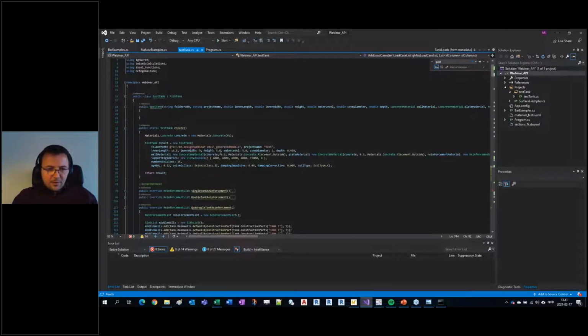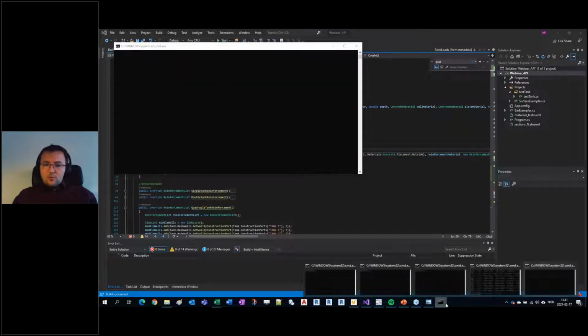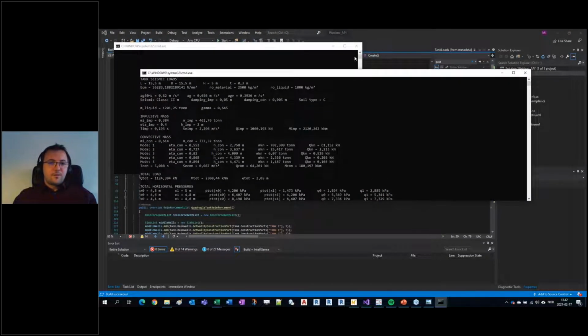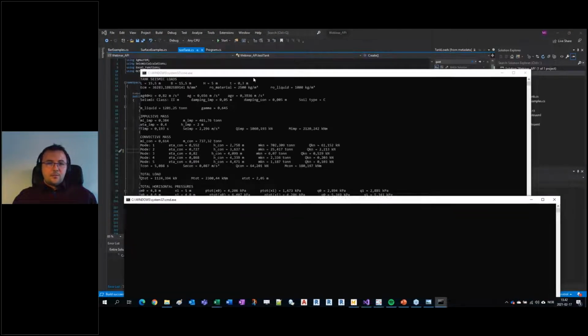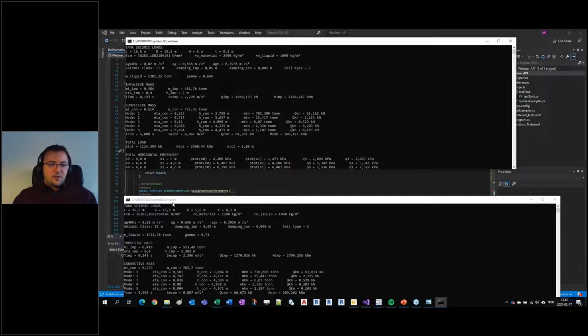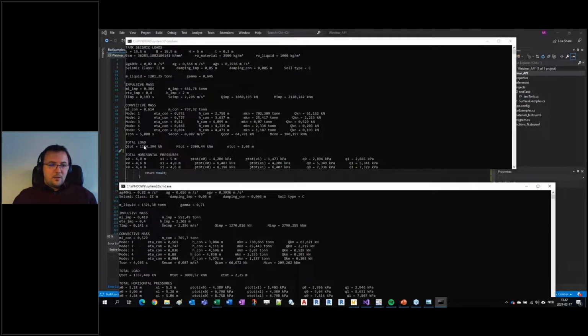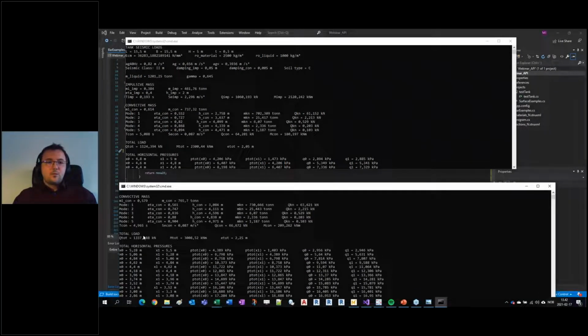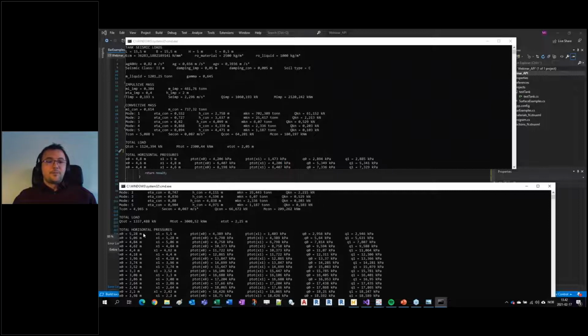Let's change my parameters. 6.1, and let's increase the height by half a meter. One would think, why even bother with a change of half a meter? But here the seismic load is incorporated in the whole application. And you can easily see that the total load is almost 20% higher for increasing the water level by only half a meter.